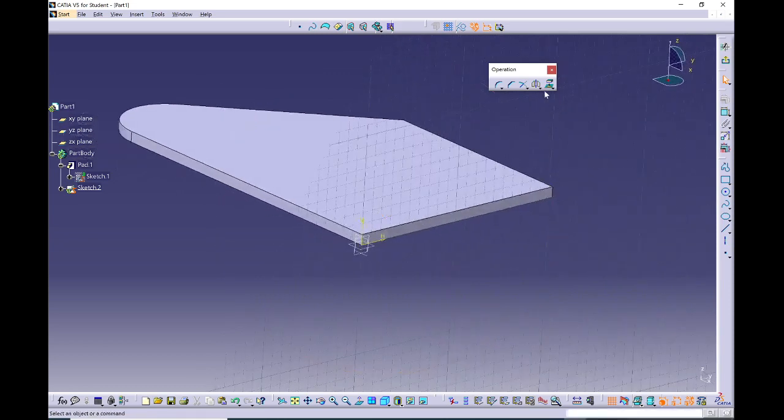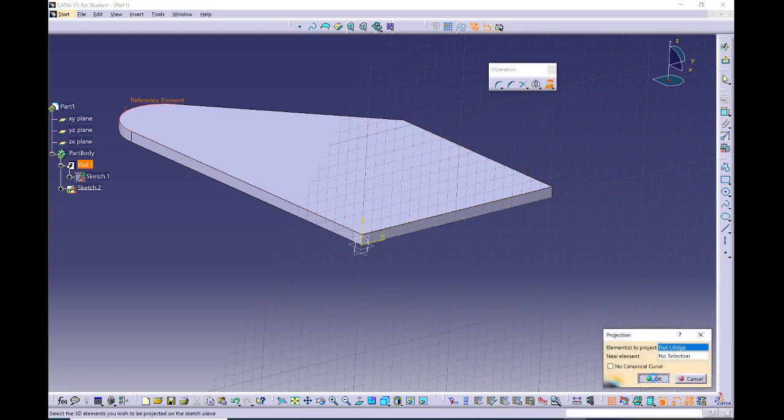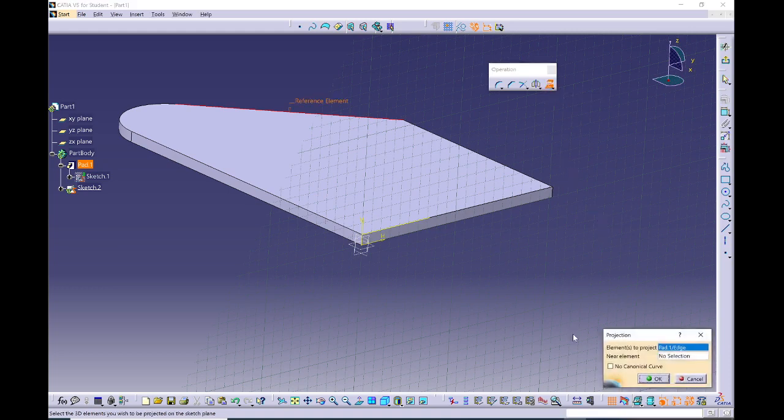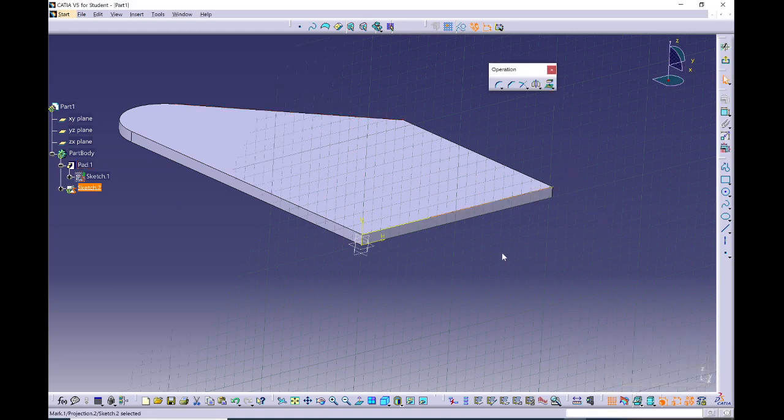Okay, so I'm going to show you that I can project this arc. I'm just going to project it and flatten it out because it's 2D. And let's project. And okay. I click in space to deselect. So you can see it brought the arc. So it just projected the arc and it flattened it out because it's a planar sketch, 2D sketch. I'm going to now project this edge just for practice. You don't have to do this part. It's just to show you what happens when you project something. And okay, it projected that edge into my sketch. So it projects normal, perpendicular to my sketch.